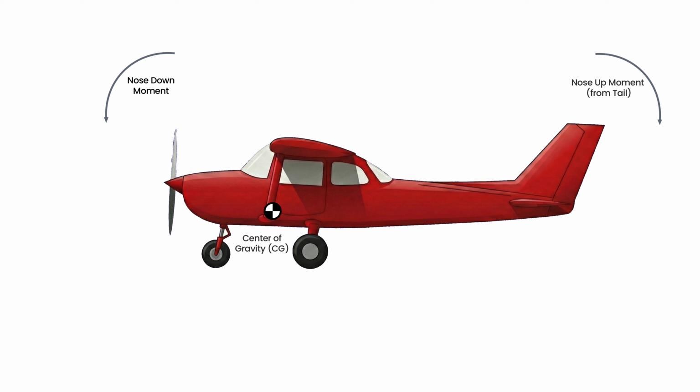If you watched my earlier stability episode on this channel, this should sound familiar. Trim doesn't exist outside the airplane's stability system. Trim interacts directly with it. Stability is fundamentally about what are called moments, forces acting at a distance. The airplane's pitching behavior depends on the net pitching moment about the center of gravity, and that moment varies with the angle of attack. This brings us to the core concept of what's going on aerodynamically.